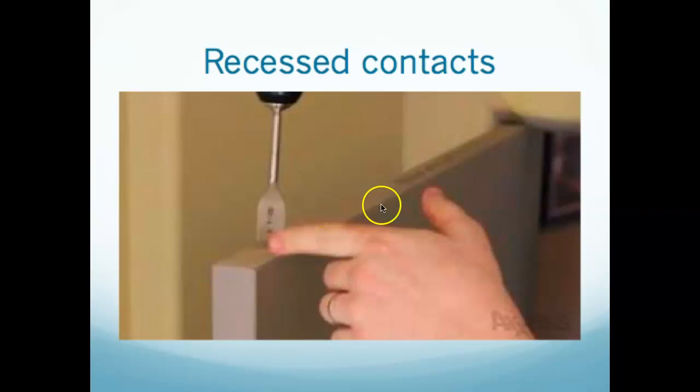And again, if you look at a door as you go through that you assume to be alarmed, if you don't see the surface mount contacts, look up in the frame of the door as you go through, and you'll see a little 1-inch plastic circle. And a lot of times you'll see doors that are drilled for them, and the alarms have been removed. You'll just see a hole there. That's what it's from. And then if you do that, just reach up to the top of the door and feel, and you'll feel the other circle right up in the door, and you'll be able to tell that that is indeed an alarm door.